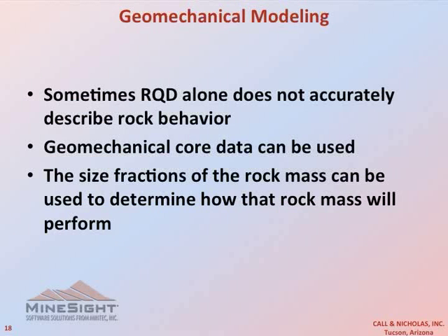When either we or our clients log core, we tend to gather not only several different sizes of RQD, but we also collect percent whole core, percent broken, and percent rubble. And the difference between broken and rubble is really just the size. The broken is greater than half-inch size. So when we collect all that data,